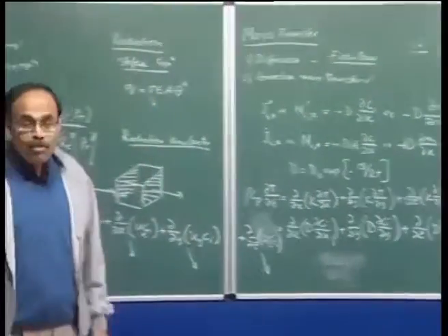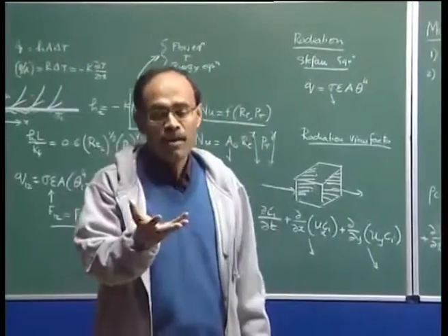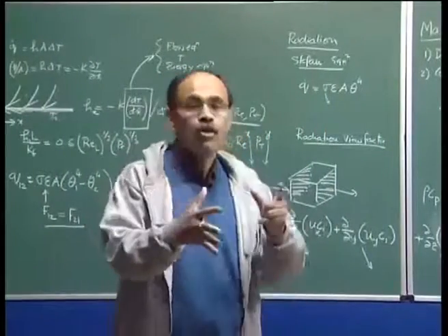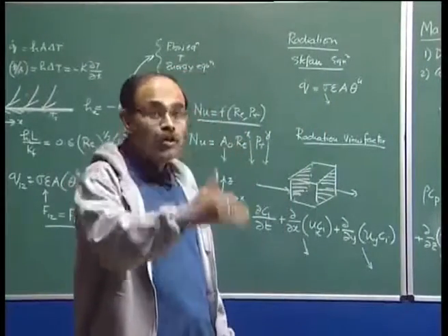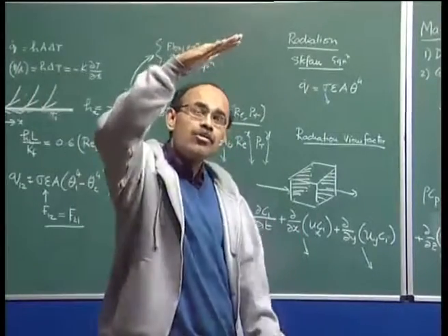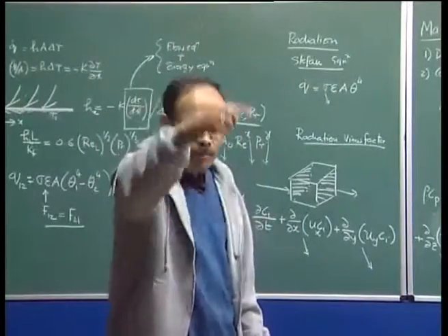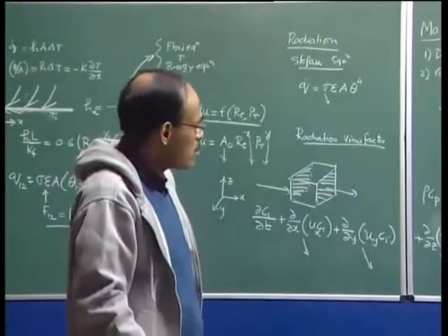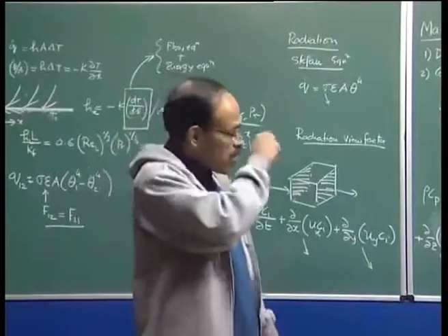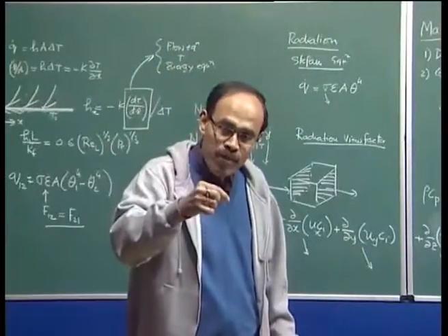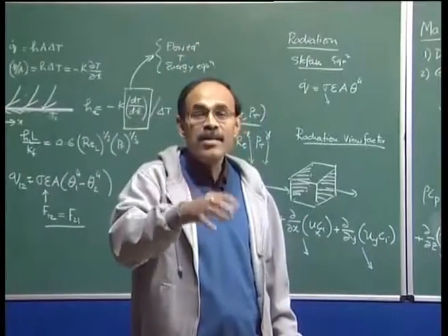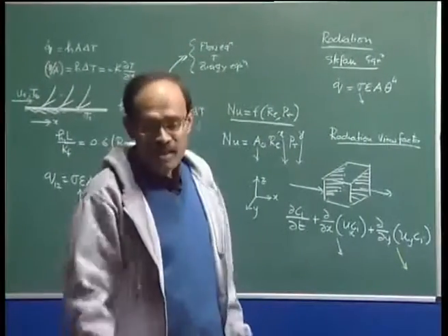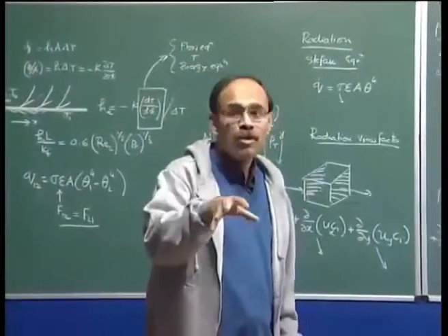Now, just like the way we had free convective heat transfer and forced convective heat transfer, we have free convective mass transfer and forced convective mass transfer. Because of thermal gradients we have density differences in the system, which precipitate into some kind of weak convection current which we call free convection. In mass transport also, if you have concentration gradients in a fluid, those can precipitate a density differential, and again this density differential can induce some kind of weak motion in the system. So, this is called solutal convection.